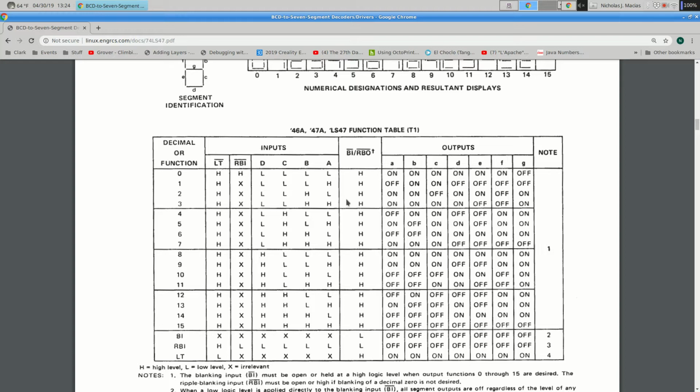Well, same thing with this. This is something that takes a 4-bit number and displays it on a 7-segment output. And so in lab 4, you're making your 2-bit adder. Your final answer, which is 3 bits, is going to be displayed on a 7-segment display. And you're just going to feed your output to one of these devices, hook the output up to the 7 pins on a 7-segment display, and it does the rest of it for you.